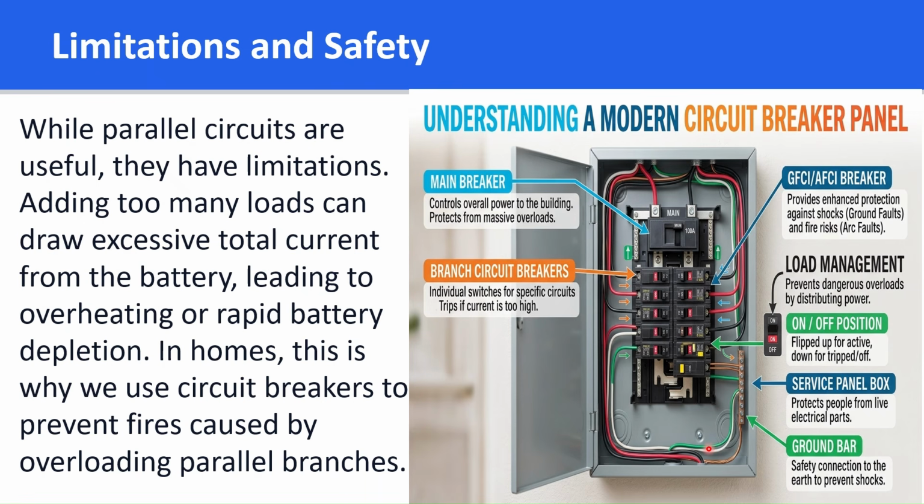Parallel circuits are powerful but can be dangerous if overloaded. More branches mean more total current. If the current gets too high, too many paths and too much current, the wires get hot. So that is the limitations of parallel circuits.